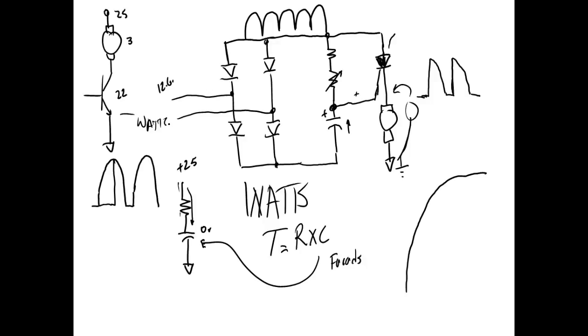Yes or no? Over here, when this guy is on, it drops 2 volts, and that's the maximum level drop, 2.2 volts. If I'm running less than 4 amps through it, it's going to be dropping less than what? 2.2 volts. So now, if I want 3 volts across this thing, this guy, when it's on, is going to drop 2.2 volts, and when it's off, it's going to drop the rest of it, but there's not going to be any current flow through it. So my SCR is going to be a lot more efficient, so it's hardly wasting any watts, right? You understand?